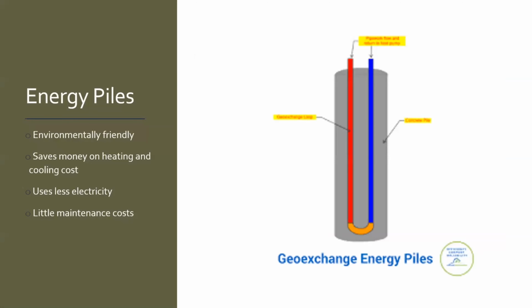The other alternative is energy piles. The pile shape is the same as if you were to design it normally, but you run a pipe through it for water to go through. At some depth, the temperature in the ground remains the same all year around. Water from a heating and cooling system goes through the pipe, and as it circulates will reach this average temperature, which is ideally going to keep the building at the same temperature all year round.